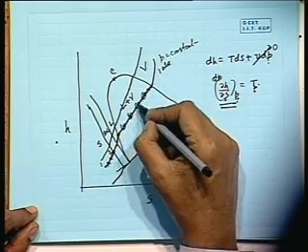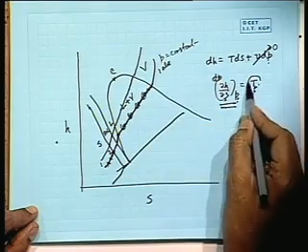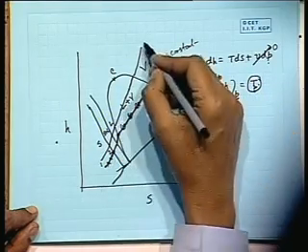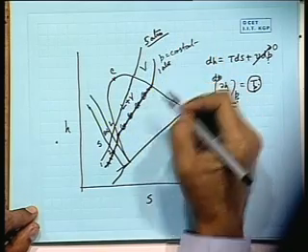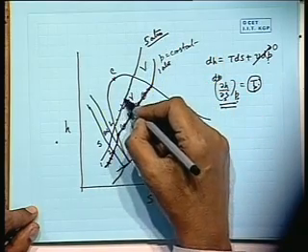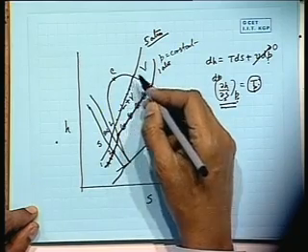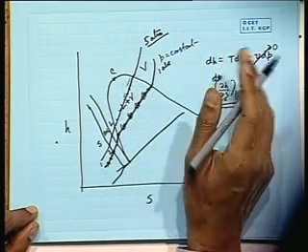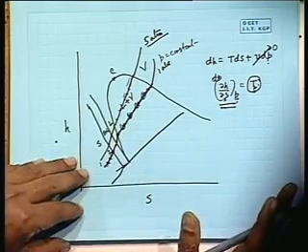All these points correspond to 100 degrees Celsius temperature. That means the slope corresponds to this 100 degrees Celsius. Whereas if it is 5 atmospheric pressure, if the saturation temperature is 150 degrees Celsius, that means this temperature is more. That means the slope of this linear element is more. So they are diverging in nature. Alright, this way we can construct the HS diagram.